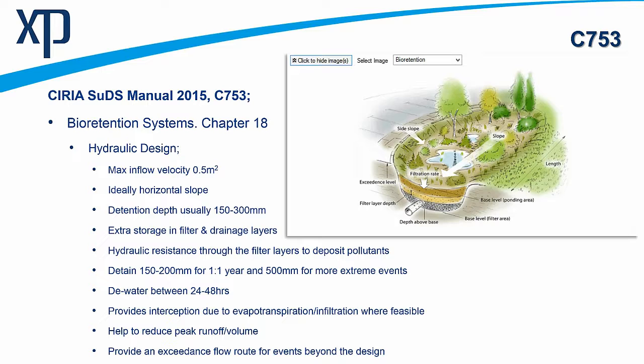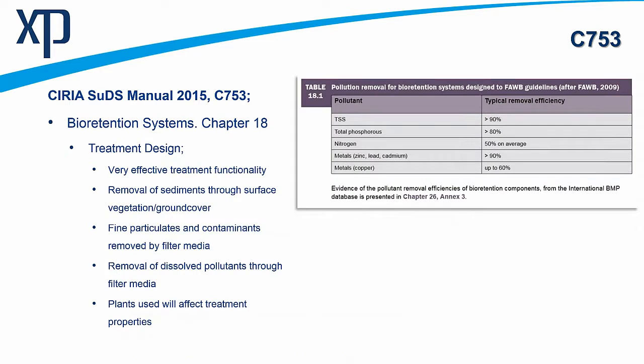We also need to provide exceedance routes for those events that go way beyond the design. So I'd go for the 100 year, I'd add in climate change, and now we're looking at surface water management. It's not the design of the structure now. We're looking at handling the surface water way beyond the design and taking that flow safely away from properties and maintaining the infrastructure of the development whilst that flow is being taken away.